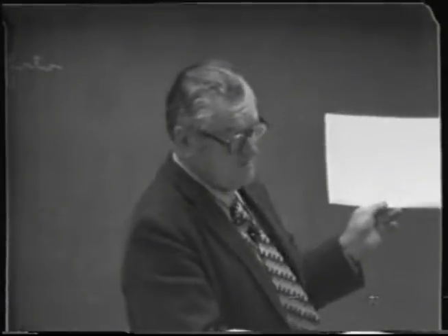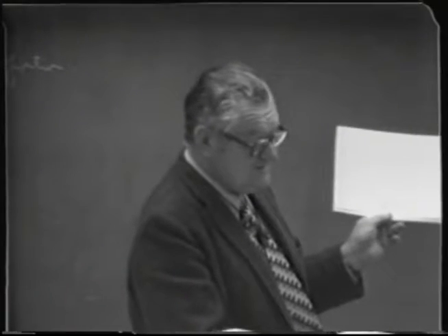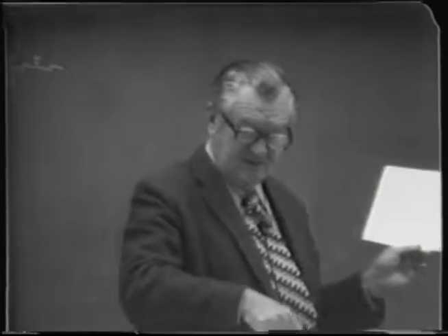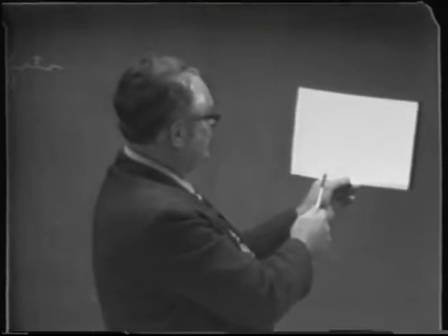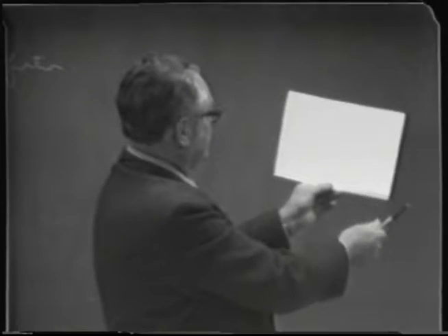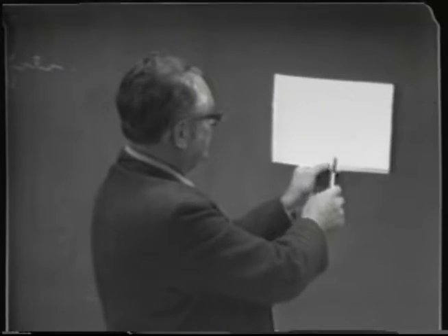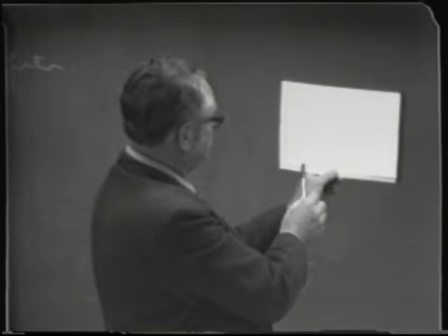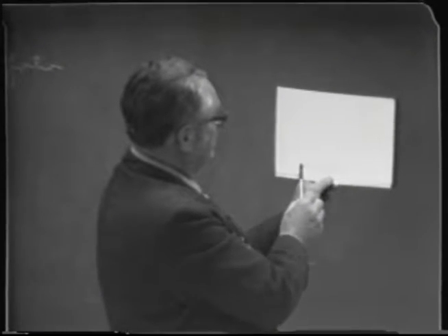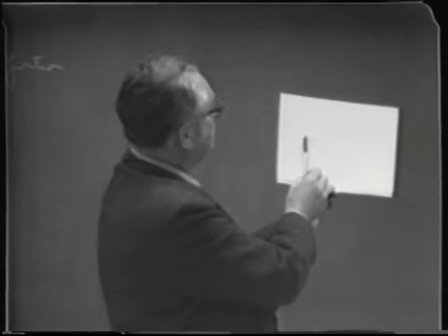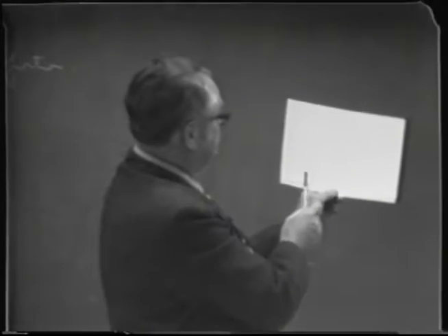I didn't hand out to you, but I have also plotted the same system on a weight basis. You can plot these on a weight basis as well. Since the molecular weight of isobutyl alcohol is considerably higher than that of water, it makes the volatility somewhat more impressive. Here, for example, is the vapor-liquid equilibrium curve on a weight percent basis. So here you see at very low values of isobutyl alcohol in water, you have a very great enhancement of the volatility on a weight basis.